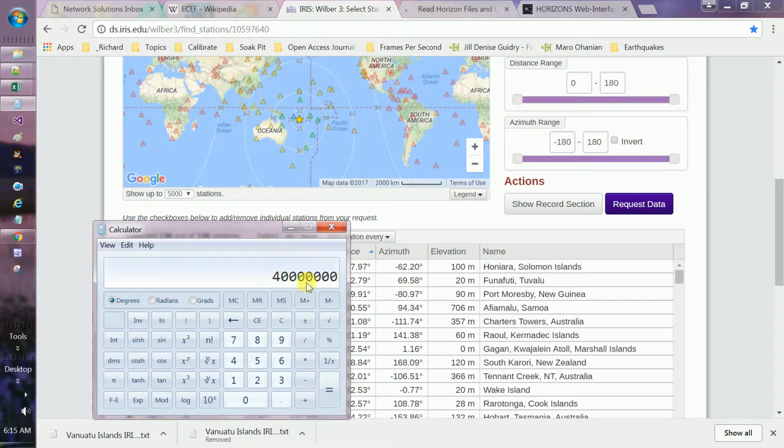If you're doing it at gigahertz frequencies, it's trivial to set. You calculate the geometric distance. You work out the delay in samples that you need to shift the signal, and then you start looking around.